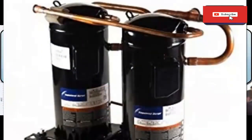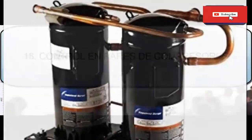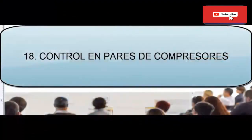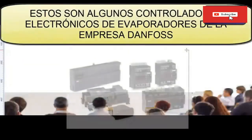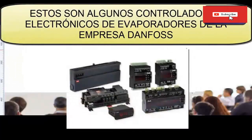18. With an electronic evaporator control, the time delay for the coupling of two compressors can be controlled. The settings indicate the time that must elapse from the activation of the first relay until the activation of the second relay, which controls the compressors. 19. Choice of the connection method for the operation of two compressors, either sequential, first to connect, last to cut, or cyclical, with equalization of the ignition time. 20. In addition, the use of the electronic evaporator controller allows the management of parameters such as: